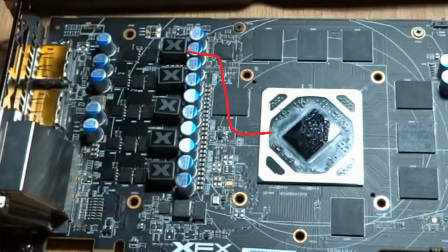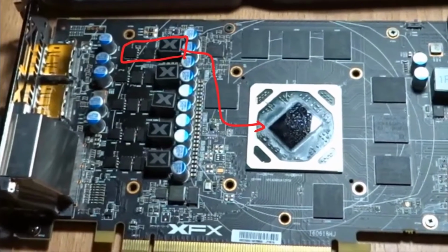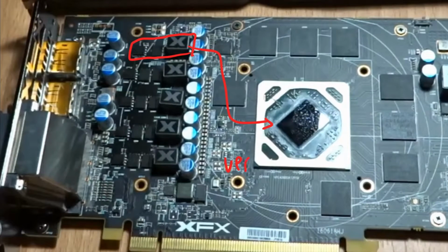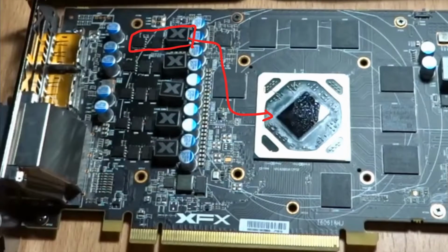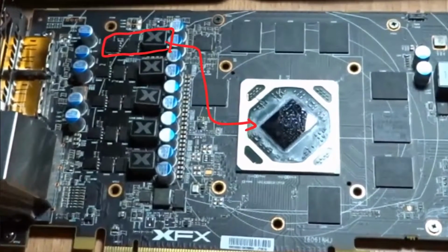And that's very likely what this one phase is right here. That is your VDDCI rail. It could also be something different. It could also be your PLL rail. NVIDIA calls it one thing, AMD calls it another thing. Basically, it's just the power rail that powers your PCI Express interface. But I think your PLL rail is this one here, this little unassuming VRM. So yeah, that's likely VDDCI, whereas this down here is vCore.